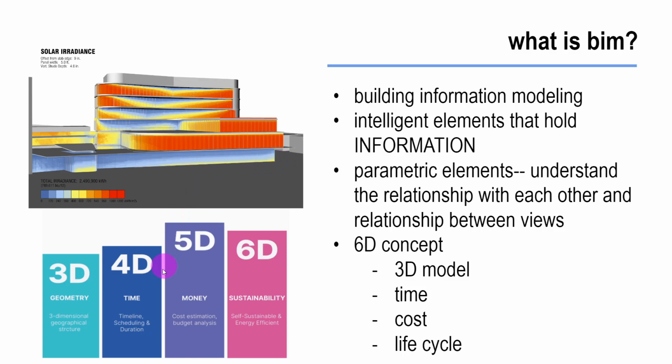But what BIM can also track is a 4th dimension, which we call time. So within all of those different elements and parameters, I can start tagging things and I can relate them to a time frame of when certain pieces will be installed, or when the concrete will be poured, and then when the concrete will be set. When can I start construction on the actual floor frame? When are my windows set to arrive on a site so that they can be installed?